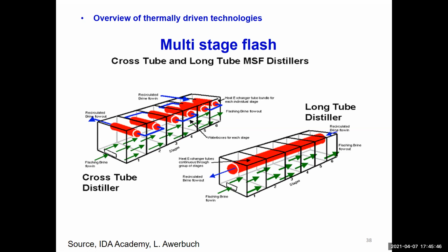So in terms of maintenance, it's fine. The problem associated with this layout is that the pressure losses are huge, because we have so many minor losses. We have bends. This kind of blue thing normally extends outside the stage, and it is normally not insulated. So it may be made of a material like stainless steel that has a thermal conductivity of 15, which is not very high.